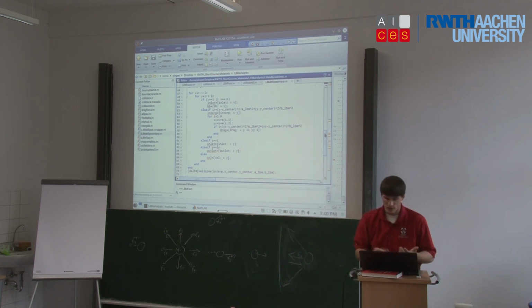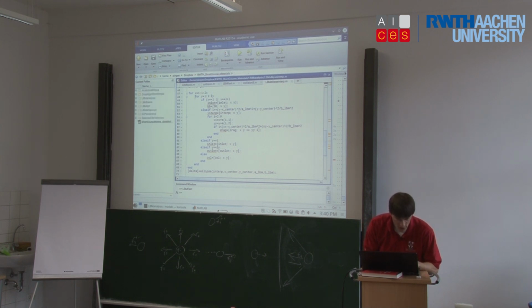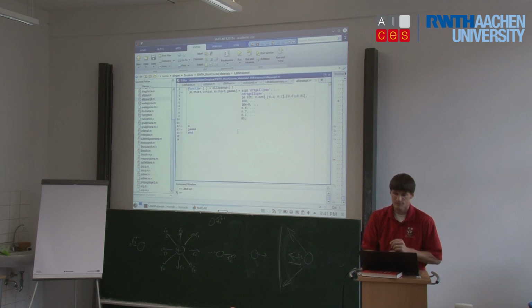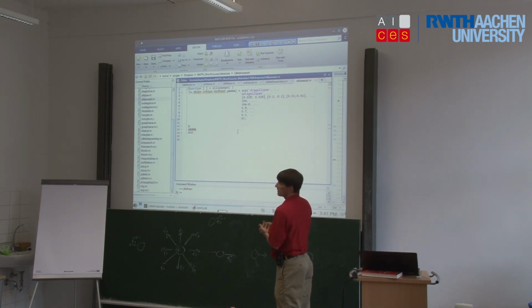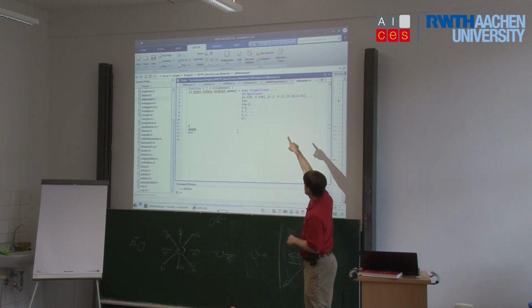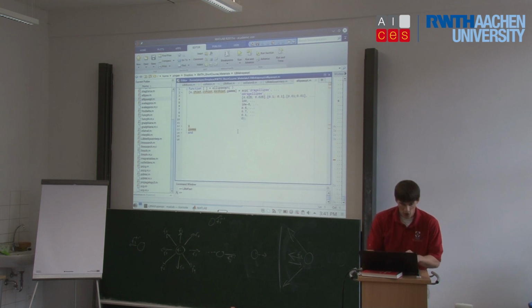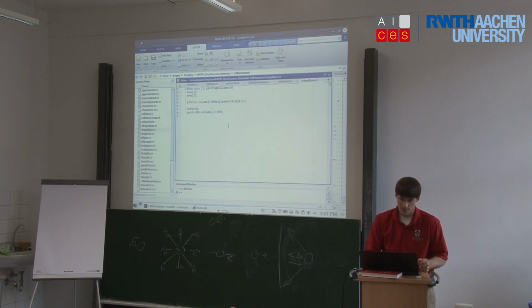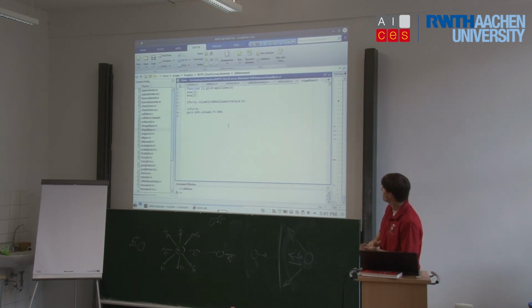What I can do now is we can take this program and we can solve it as a shape optimization problem. So if we go to the algorithm called LBM shape opt, and we open the program ellipse opt, okay. Ellipse opt now, rather than using the analytical model which we used earlier in the course, uses the Lattice Boltzmann method to evaluate the drag of the ellipse. Drag ellipse, okay, calls the Lattice Boltzmann program LBM ellipse interp with given A and B values.